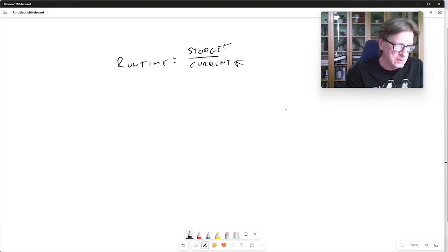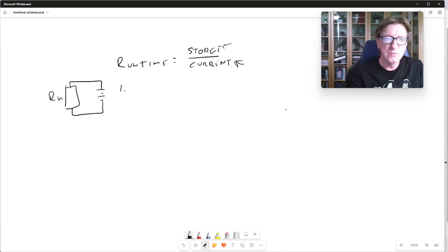All right, so let's take a look at the first scenario. In the first scenario, I've got my microcontroller, my main board, and then I've got some battery here. So here's my load. This is my microcontroller. And this is the battery that's being provided for it. And we tell you that the battery is rated for 1.8 amp hours. That's written as amps times hours. And the voltage is going to be 5 volts because that's what our microcontrollers all need. So they're going to have to be connected to a 5 volt source. And what I want to know is, what is the runtime?